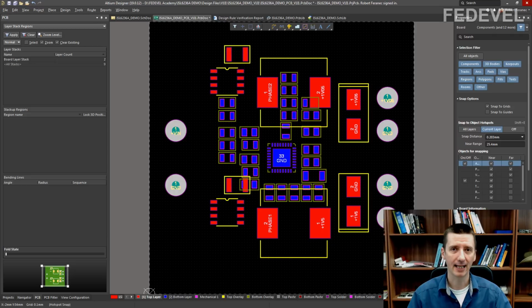When you are doing PCB layout, especially layout of very complex boards, you may want to hide all the unnecessary objects which are not really needed for PCB layout. Because when you have a very complex PCB, there is going to be a lot of stuff. So you really may want to think what is really necessary to see in your PCB. And one of the things you may want to hide is the grid. You don't really need to see the grid when you are doing layout.